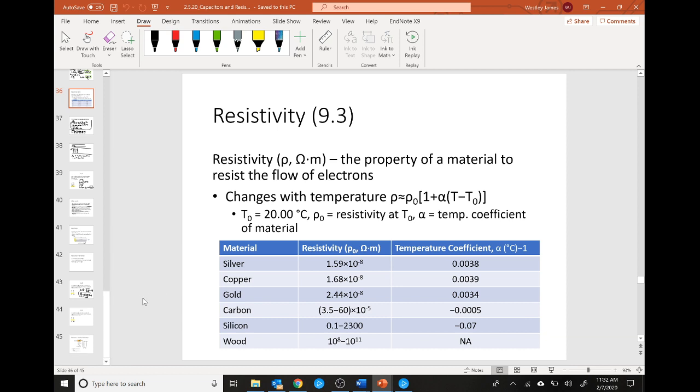The last thing I quickly tried to say to you all, and I mostly got through, is that when you're actually in the real world doing this in engineering, the type of material you use is not just based on, oh, this has the lowest resistivity, so that's the one I'm going to choose. No, you also have to factor in cost, how it's going to behave in the environment it's in, and if it's going to react to whatever thing. So for the easy examples, if I use iron as a wire, it's going to turn into rust, and rust is not very conductive, so you end up not having a good thing, whereas gold is non-reactive, and that's why most of your fine circuitry in your devices is gold for that very reason.